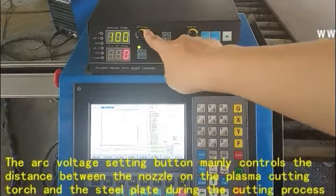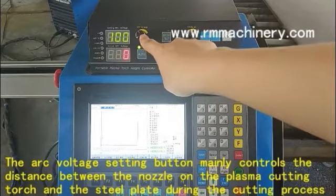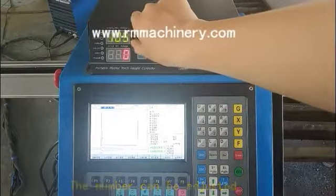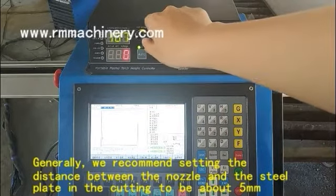Arc voltage setting button mainly controls the distance between the nozzle on the plasma cutting torch and the steel plate during the cutting process. The number can be adjusted. Generally, we recommend setting the distance between the nozzle and the steel plate in cutting to be about 5 mm.